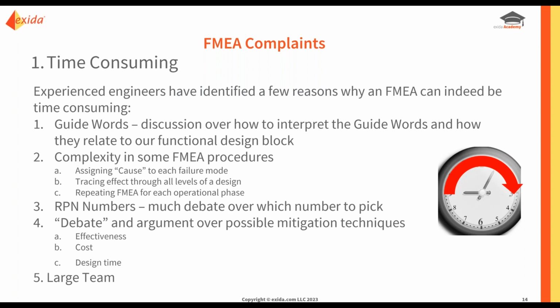And lastly, I've seen the FMEA repeated for each operational phase of a product, you know, normal operation, maintenance, and that's okay, but I do recommend separating them into separate FMEAs with different people. Trying to get everybody in the same large group just takes more time.